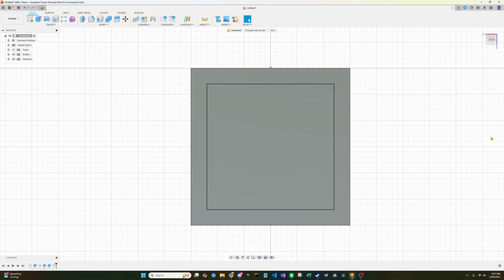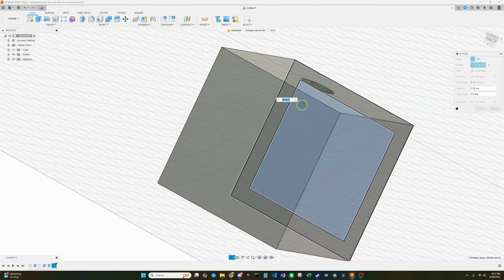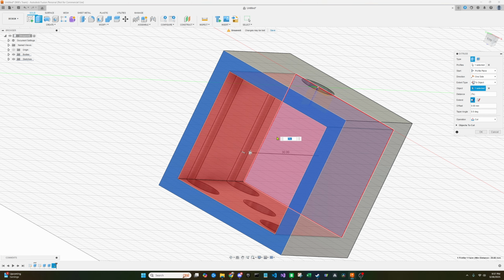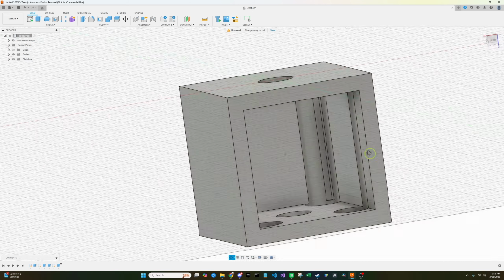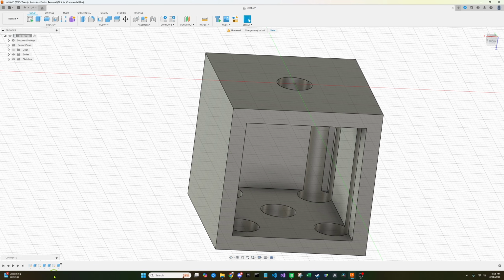And now we're just going to go ahead and finish the sketch. So now we can go ahead and select that center point with our extrude tool by pressing E. And we're going to set it to 3 millimeters from the edge, -3. So you can kind of see the idea here. We kind of have a shell. However, there's a better way to do it.